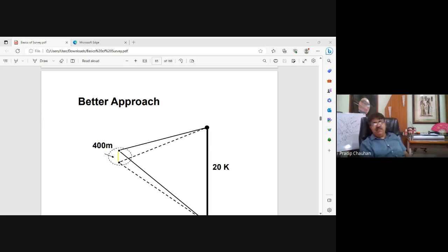So levels are very much important, and volumes are important. If there is an embankment, you have your ground profile and your proposed levels, might be in topsoil. In earlier days, we used to take chainage at 5 to 10 meter, work out area A0, A1, A2, area at 5 meter, area at 10 meter, area at 15 meter, and then using the average coordinate method and Simpson's rule, work out the tentative quantity of earthwork on top of that profile.